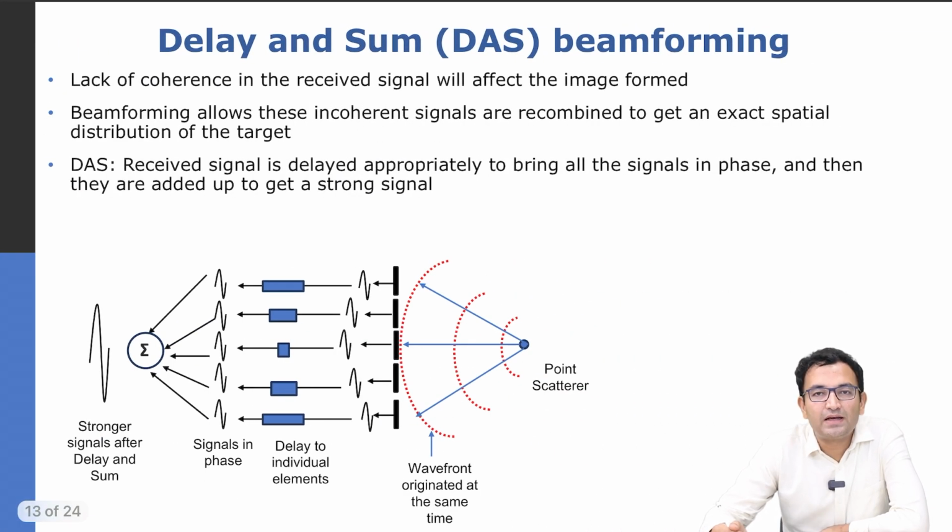We discussed the most basic beamforming in the last lecture also, pen and paper. We discussed delay and sum beamforming, just jogging your memory here. We said that because the signals have to be added in phase, there has to be some way through which the signals will be time compensated. The simplest way is to use geometry, and we assume a standard speed of sound for soft tissue, which is an average essentially of 1540 meters per second. Using that and using essentially geometry, we provide different delays,